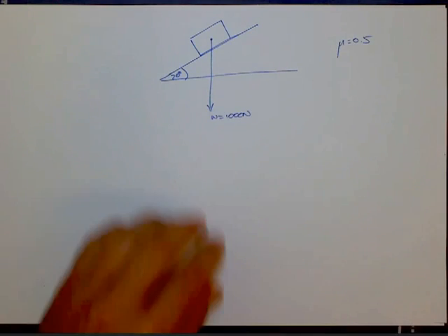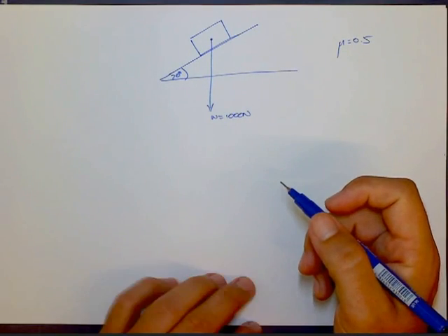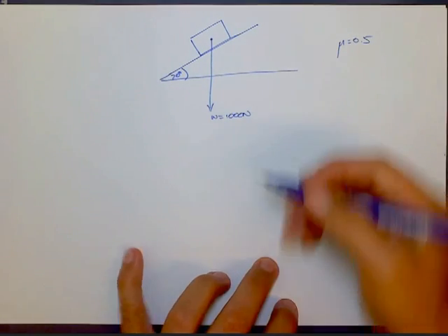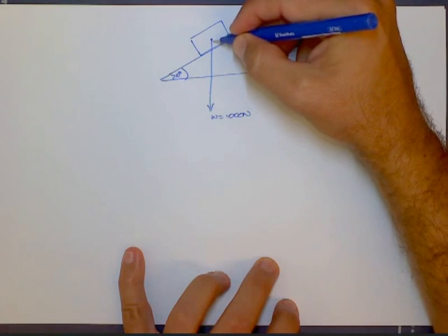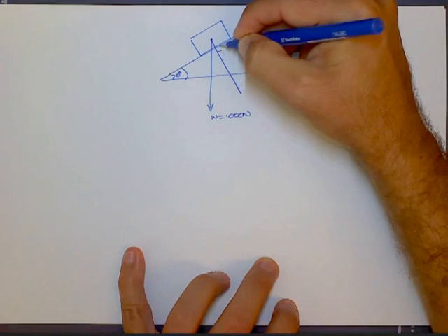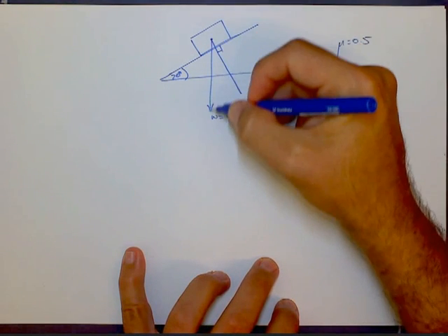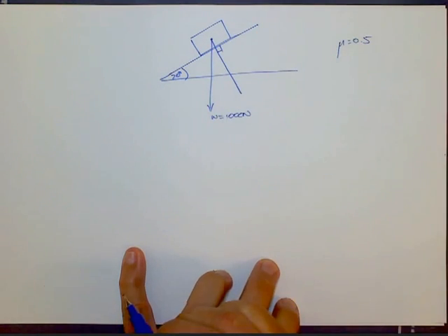So what we're going to look at here is, once we start inclining a plane at 20 degrees, the important part is that we know that the normal reaction is a reaction which is perpendicular to the surface, which is what we said last time. And so in this example, the weight force is not equal to the normal reaction, and that's the most important thing that we need to remember for this point.